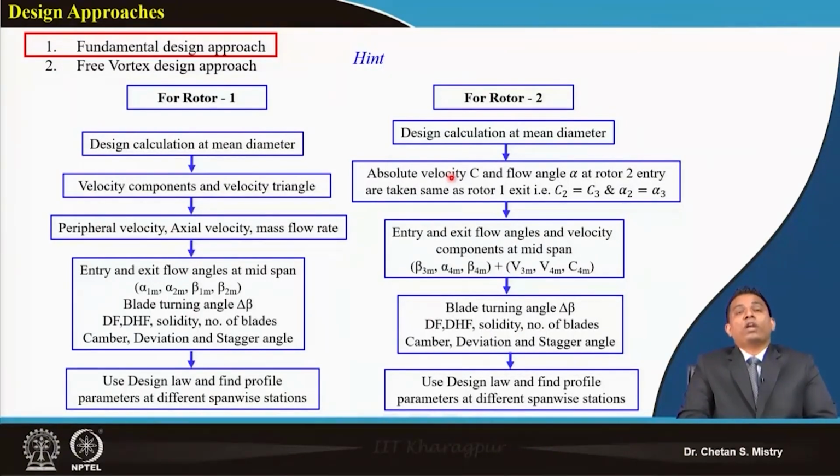Now, in line with rotor 2: for a conventional stage, as we have discussed, we have a rotor and stator combination, and for that we calculate the velocity with which the flow comes out from the rotor, that is the absolute velocity C2. That is what we assume is going to the stator. In line with that, for the design of the contra-rotating fan, listen carefully to what we will be doing.